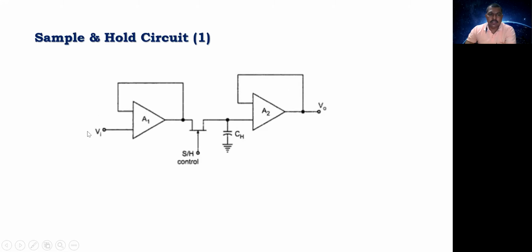So we are having this analog voltage. We are inputting analog voltage over here in this op-amp, and this is being sampled. This is a holding capacitor over here, to hold that particular data, and this is the switching element. Right, here we can use a BJT also, bipolar junction transistor also. So this circuit is going to be used in between the analog signal as well as the analog to digital converter circuit, right? In between that.